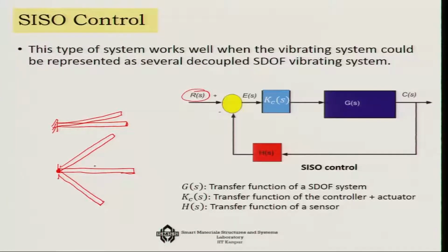Now, this is the rigid body movement, this is the reference signal that you are giving to the system. The reason for applying active vibration control in this system is that, due to flexibility, while moving it can start to vibrate. So, it may give you various vibrating modes. That means you will lose the pointing accuracy corresponding to various types of vibrations. So, that is where the reference signal is to be strictly followed and the active vibration control signal has to work.